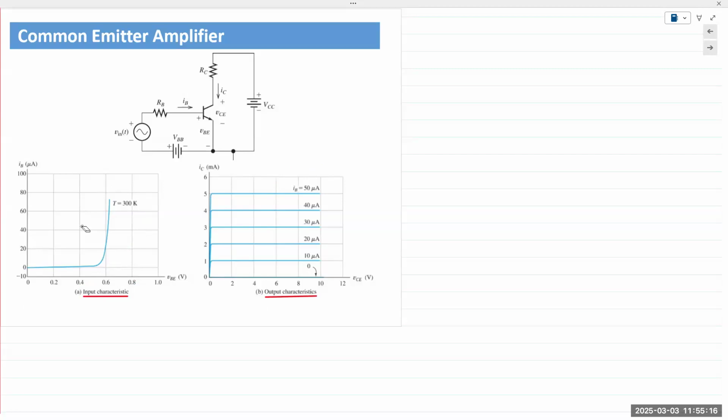What we would do is apply KVL on both sides. We apply KVL to the input side and to the output side. And we generate our load line to obtain 2 points on the input side, and then we generate a load line on the output side. Then we use this to solve for the AC input signal.